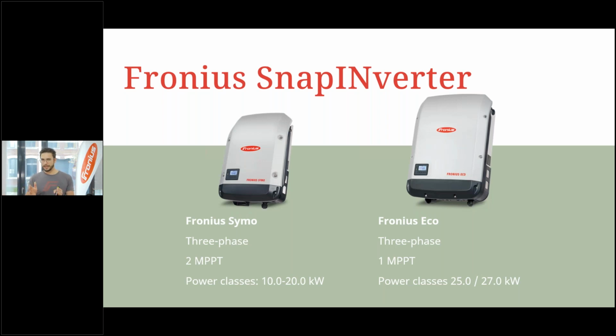It is then a little bit limited, so we have not such a big DC operating range, but it's perfectly fine if we have a big system on the roof. This shouldn't worry us. We have it in power classes 25 and 27 kilowatt, and it has one MPP tracker compared to the Symo inverter on the left-hand side with 2. So again, we can do a mixture of those two, or we can even include the Tauro with those Snap inverters in such a system. Doesn't matter how you want to do it, you can do it with the Fronius product line.